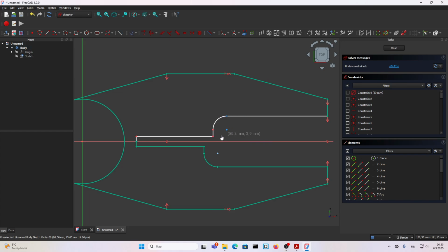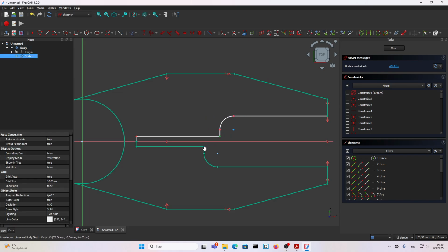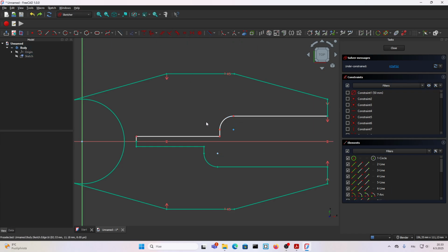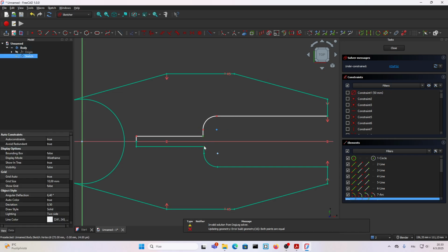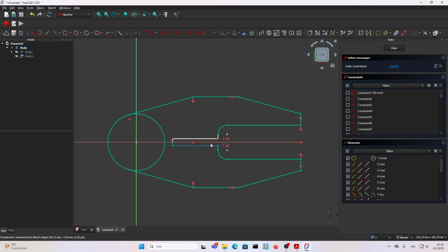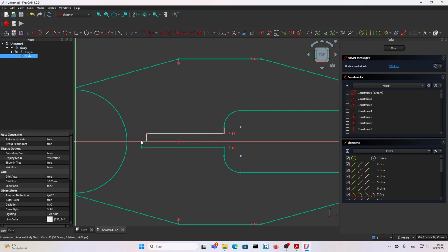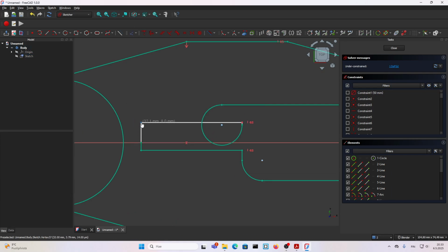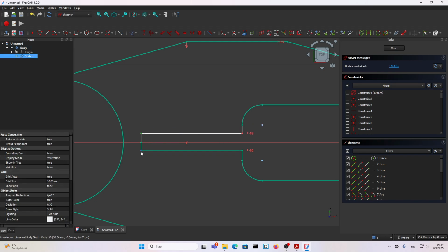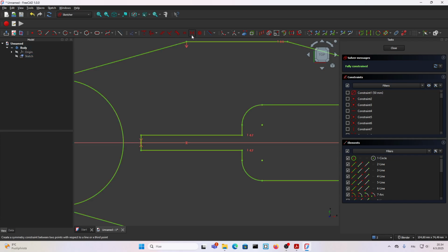If you look at this, it moves right and left only. We need it aligned with this one. Let's align it. Where was the constraint? It didn't work. I did something wrong. It needs to be closed like this here, and then I have to align it. Now it's aligned. If we look at this one, it moves up and down. First, I will constrain this dot to this using a coincident constraint, C from the keyboard, and then the symmetry constraint on here. Just like this.